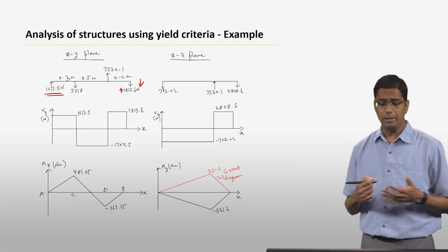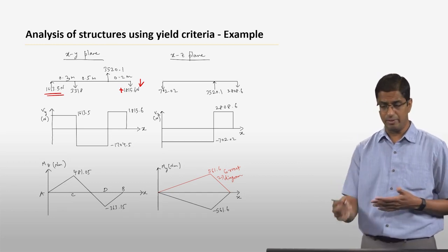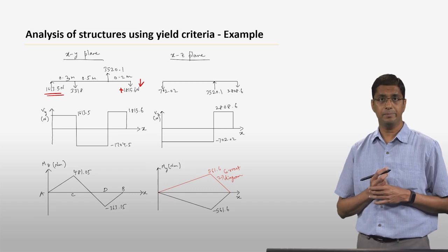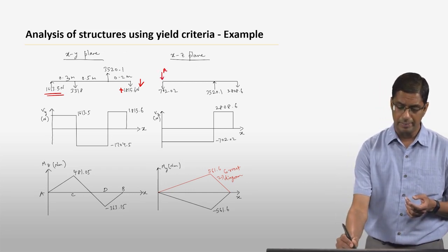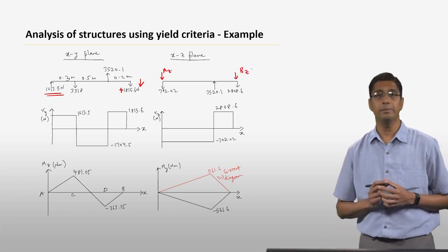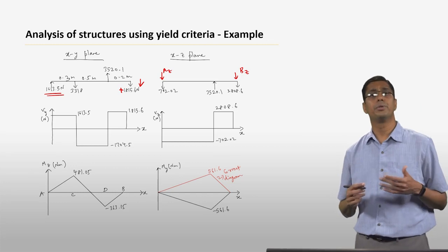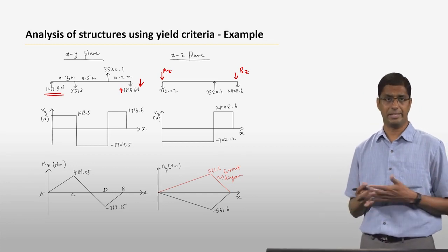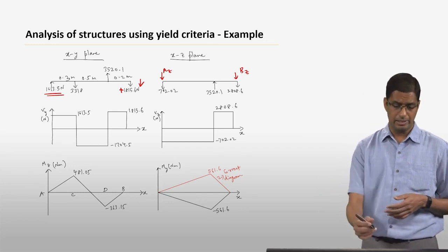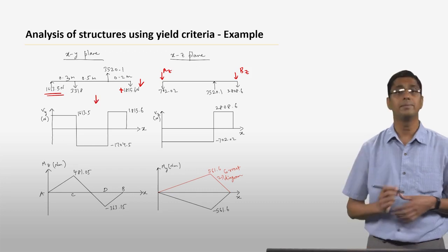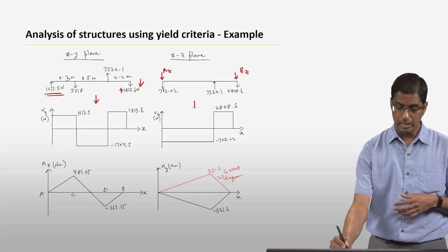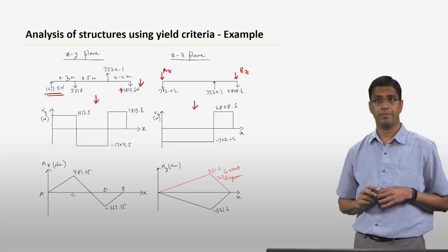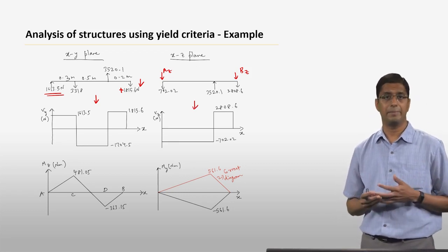Okay. Now, the same thing can be done for the xz plane, and again, both the reaction forces AZ and BZ are in the negative z direction. Okay. Now, once you draw the free body diagram with the reactions, you can easily construct the shear diagram. The shear diagram in the xy plane is going to look like that. Okay. And the shear diagram in the xz plane is going to look like that. Okay. So this is something, again, you have done many times.